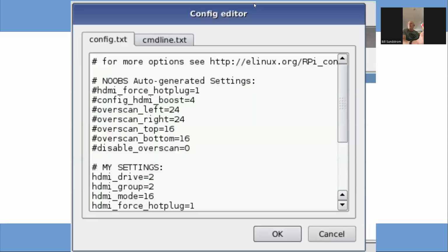The only other step is when you install the OS on the SD card, you can go in and edit a file called config.txt, which is in the boot sector that you can get to when it's plugged into a Windows machine, and modify some of the boot settings. In most cases, you don't need to, but there's a couple in there that, depending on what you want to do, you might need to change.